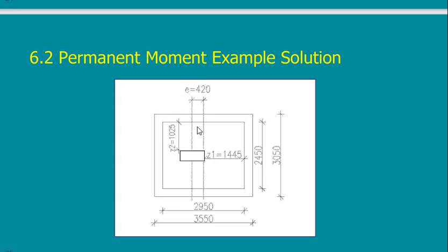So this will be similar to another problem where I have different values of cantilevers. I have to study this moment, and I have to study the other moment, and I will design the footing based on the bigger moment, and get the value of steel of the other direction based on the other moment. You got me with this? This is the only difference.